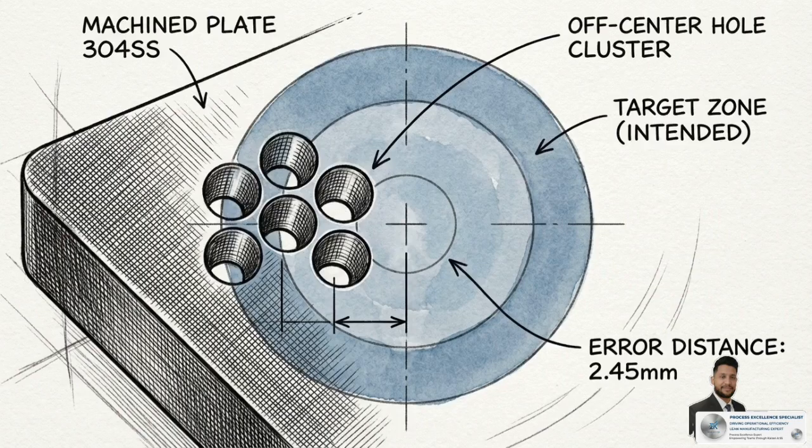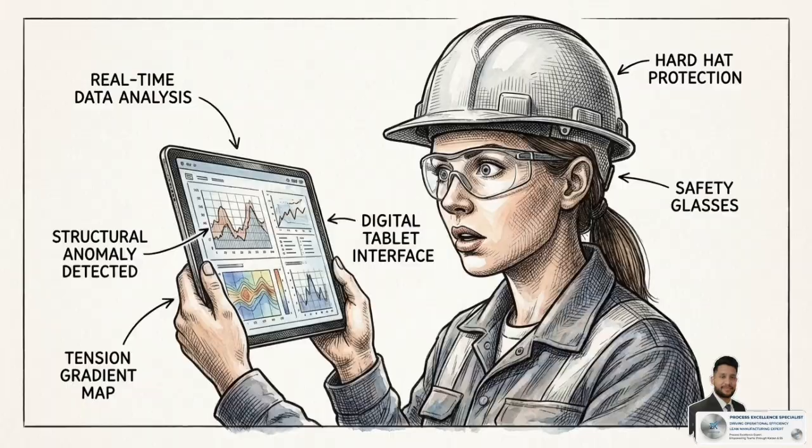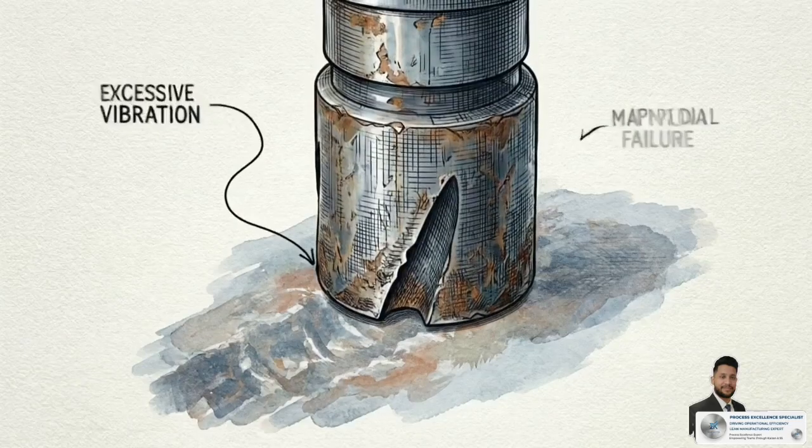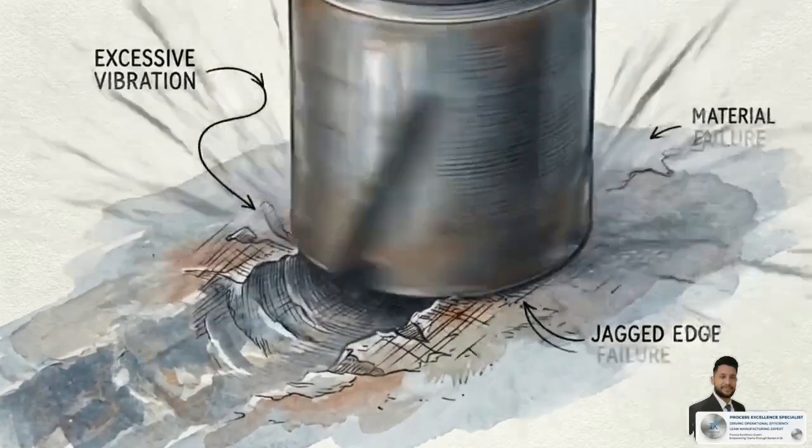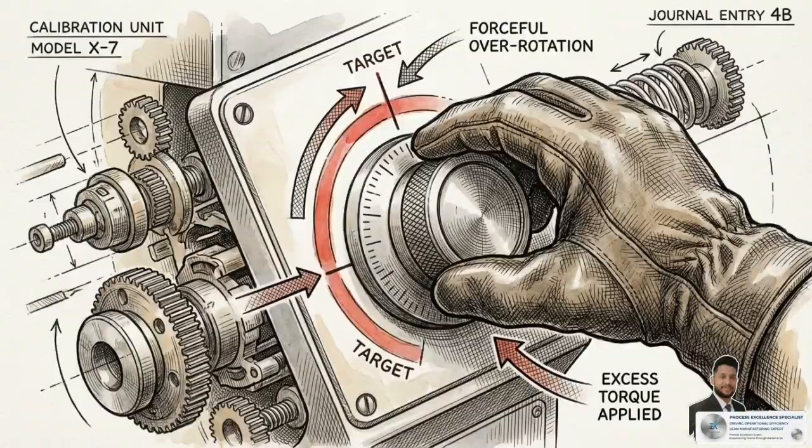The numerical gap between these two figures is specific data. It represents the exact process capability you are sacrificing strictly due to bad aim. This inviolable inequality is an instant diagnostic tool. It tells an engineer immediately whether a defect on the floor is caused by the machine's inherent lack of precision or simply due to the operator's poor targeting.